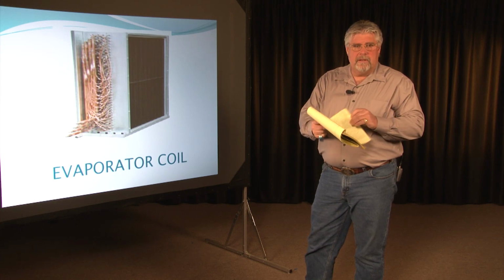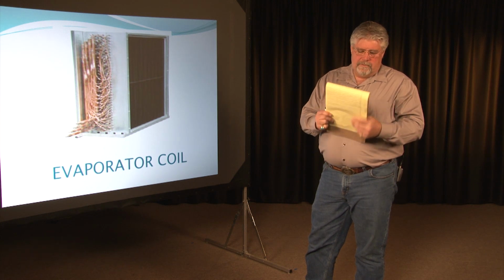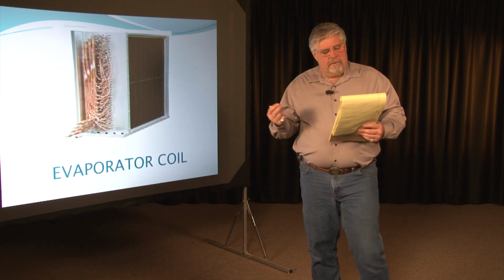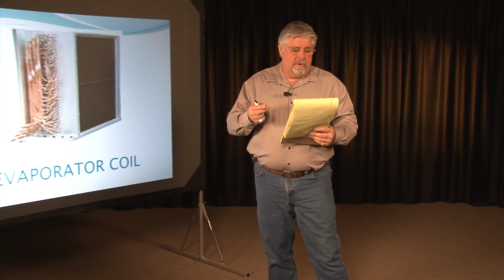I do want to say one other thing. I do want to talk a little bit about the SEER rating, and that's the rating that is used. The coefficient of performance, or the COP, measures performance, but this dimensionless measure has not been adopted, but rather the energy efficiency ratio, the EER, has been adopted, and that is what is used. This is the energy efficiency ratio based on a 35 degrees Celsius outdoor temperature.